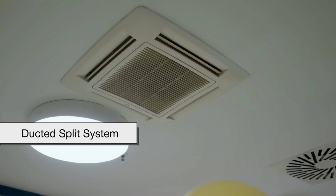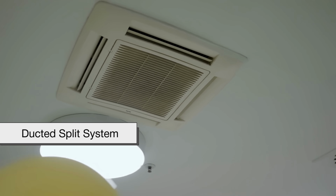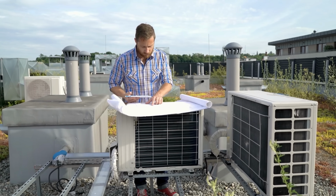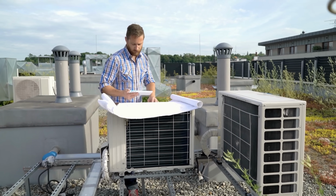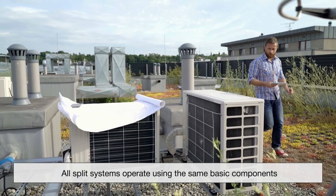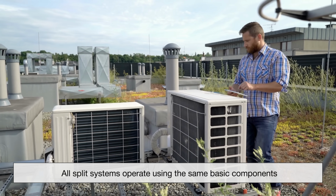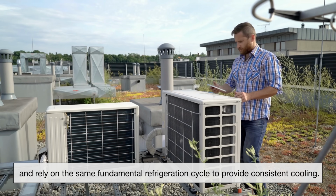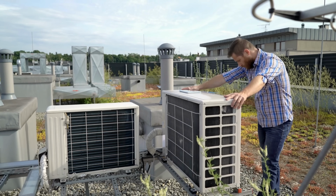Ducted split systems conceal the indoor unit in a ceiling or roof cavity, distributing conditioned air through a network of ducts to multiple areas. While each type varies in installation complexity, control options, and visual impact, all split systems operate using the same basic components and rely on the same fundamental refrigeration cycle to provide consistent cooling.